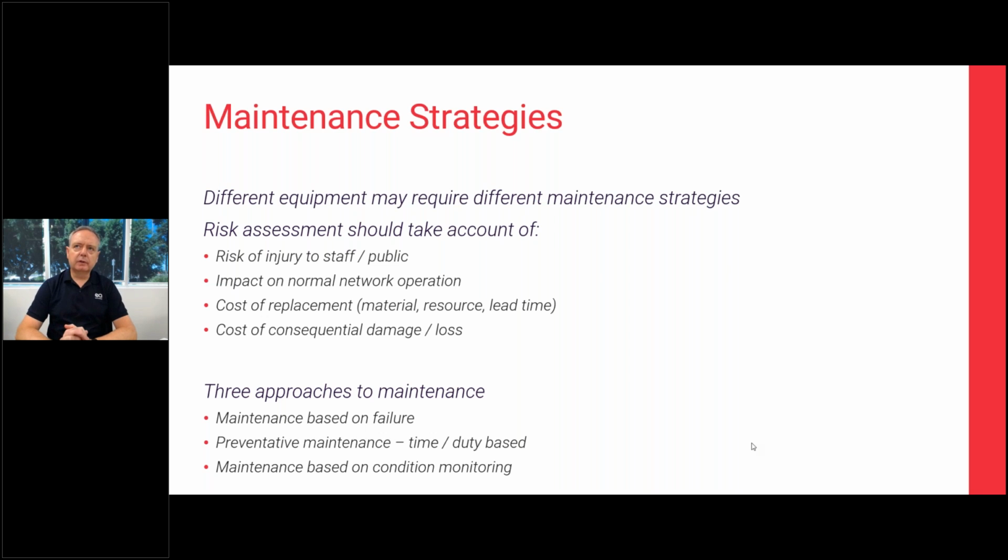Then you've got three basic approaches to maintenance. The most simple and probably least effective is maintenance based on failure. That may be appropriate for something with very limited consequence, but it is not typically appropriate when you're looking at high voltage substation switchgear or cable type assets.